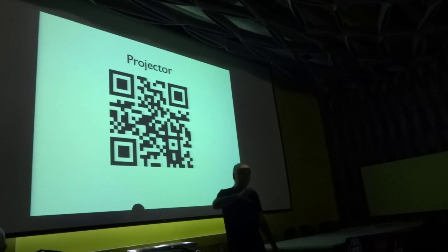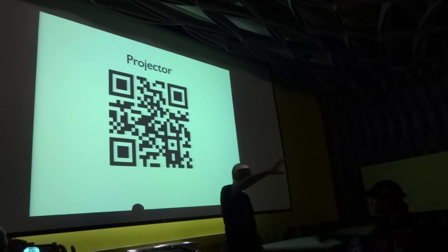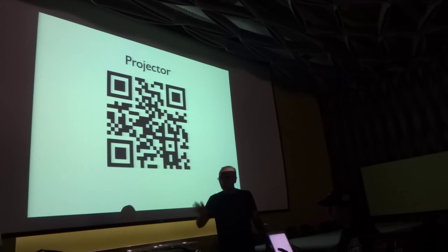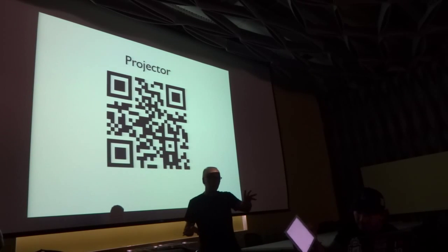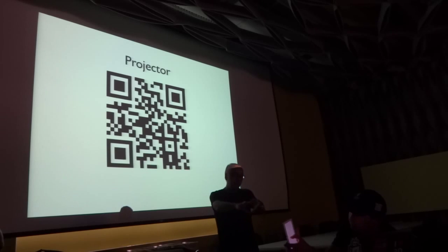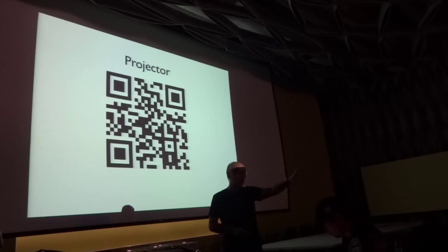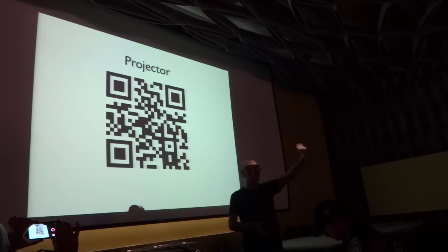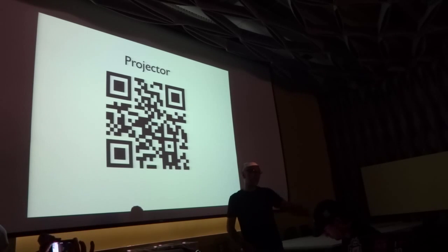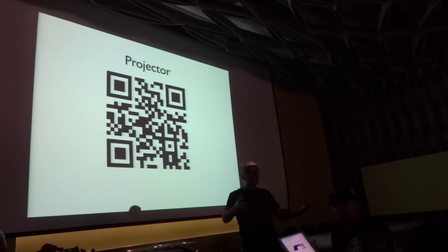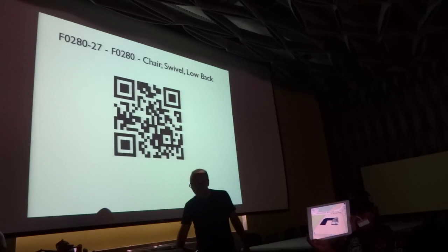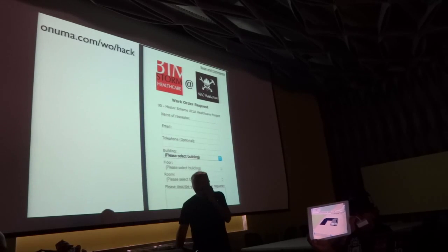Essentially, you can come and see this later on, but basically the iPad grabs the QR code that was in the database that was built on the fly when we put that projector in the room. See there? And then we scan the code, it opens up the plan, the BIM in the iPad, it finds that projector, it grabs the Atenia data that we hooked into on Saturday and says, here's the specification of that projector, the Sony projector, and so on. This happens for all the spaces that we showed earlier with the equipment. Every single one has this information associated with it.